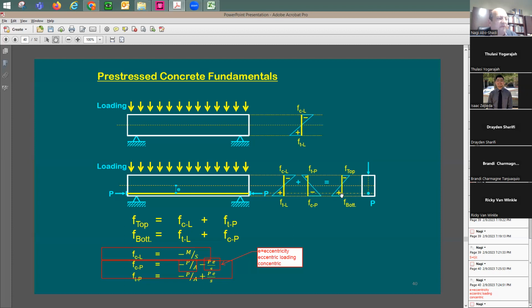But what happens here if I have very limited live load and dead load, right? The loading is going to be very small. And the amount of pre-stress is just high. So the compression value, the numeric value, is going to be high, and this is going to be very small compared to it. In a case like this, you may end up with compression stresses. So it is not true that you usually end up with some tension here and compression at the top. This is not true. It could be different. It just depends on the values. And you can play with this if you like.